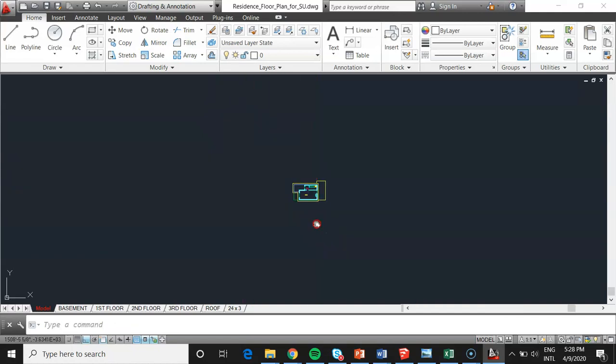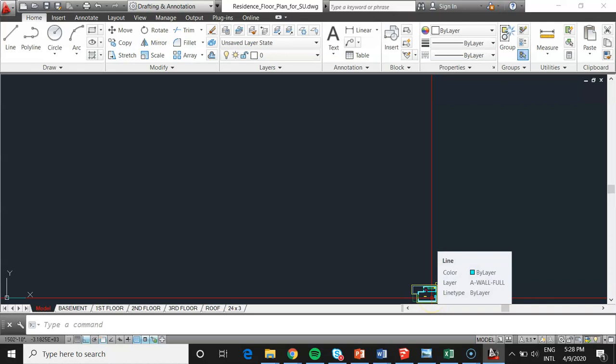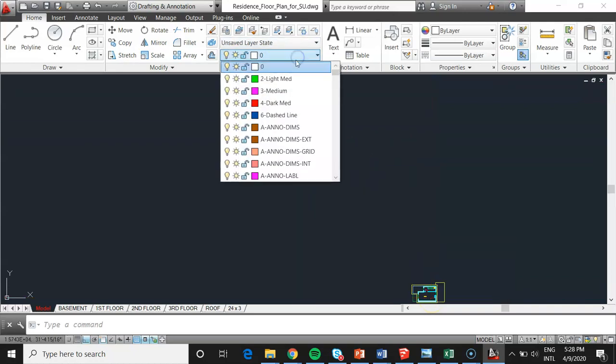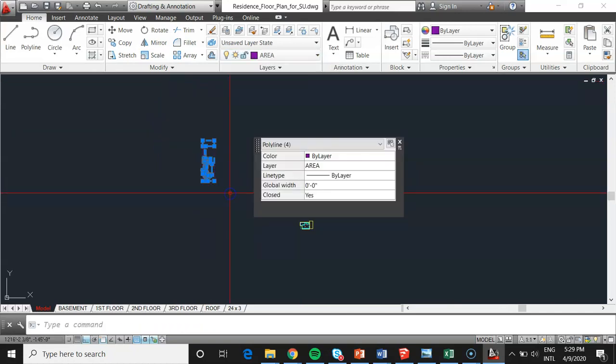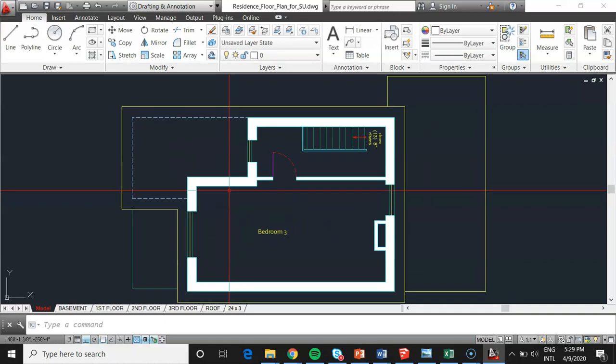Now I'm going to double click the wheel there, and that's zooming extents, and that's telling me that there's something else in this picture. This part's not coming front and center, so there might be a layer that's not on. So I'm going to scroll down through my layers, looking at those light bulbs, to see if anything is off and not accounted for. There it is, an area with the light bulbs off. Light bulbs on, and there's some more stuff. So I'll just erase that, zoom extents, and it's front and center.